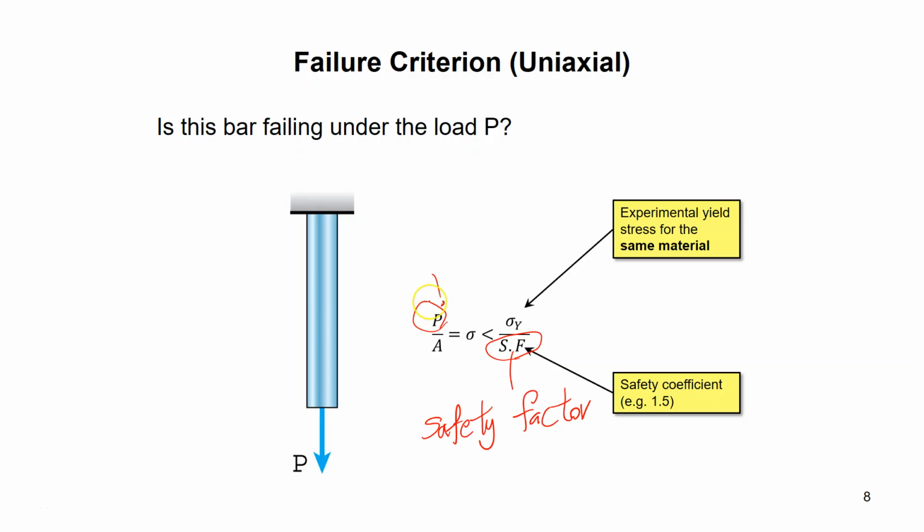You design it for 10, but 20 people jump in. And what happens? Yes, you're going to see the rope fail and kill everybody. So because of uncertainty in the force or the load or thermal or all sorts of other loading that might happen to the object, and you're not sure about it ahead of time, you cannot model it, you always consider some safety factor.